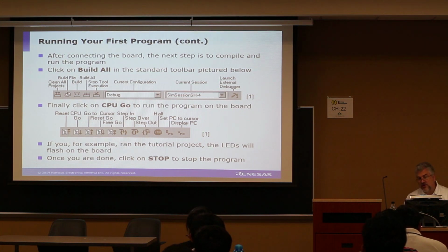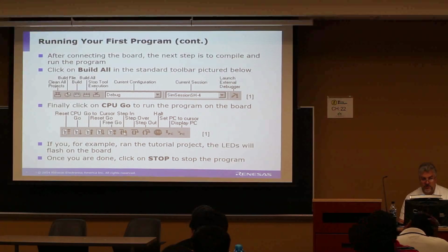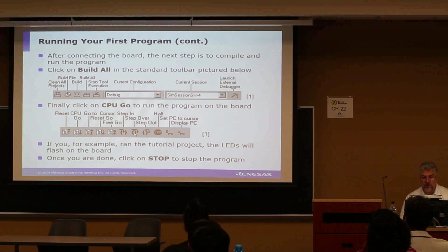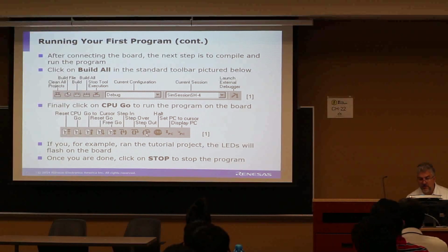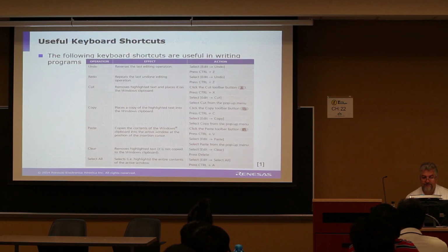As I said earlier, when you are debugging, you can reset the CPU and actually run the particular program that you have loaded. You can step in, in other words, if there's a subroutine, it will step into it, going step by step. Step over, meaning that you don't even want to execute that, or you can step out of the particular code that you want to execute. And of course, all with a stop once you're done.